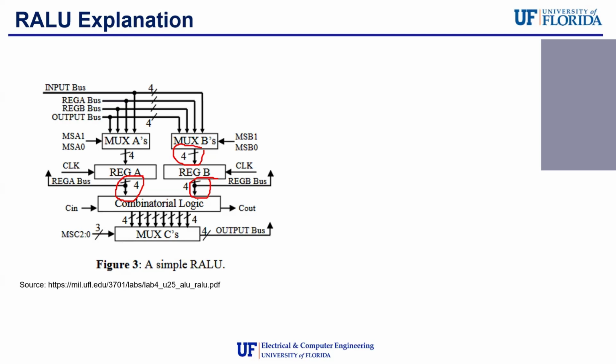Thank you for coming. I would say also try to make your BDF clean. If you do part 1 and your BDF is kind of messy, then when you make the ALU and try to make the RALU, your BDF is going to get really full really quick. So try to keep all your inputs together and make your muxes nice, so it'll look pretty nice. Use the rectangle tool to section things. I didn't know there was a rectangle tool until a couple days ago, but it's pretty nice.